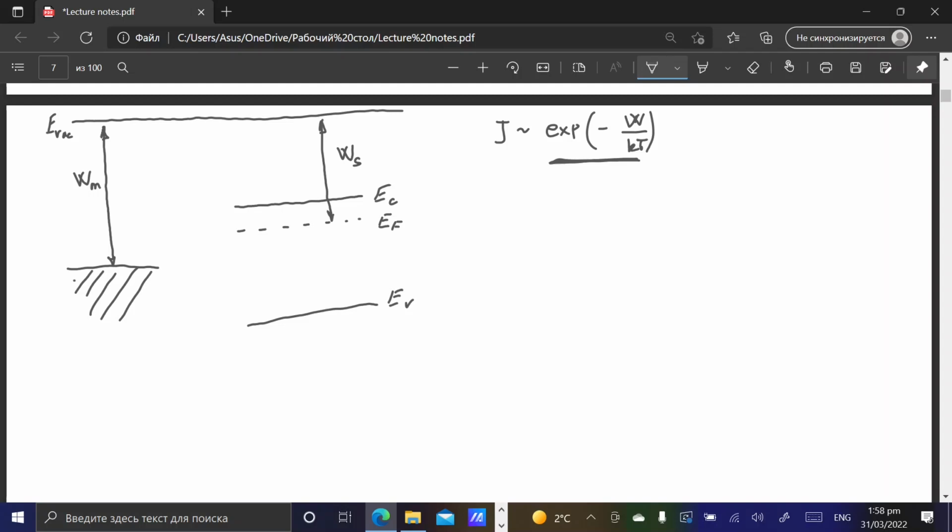So when this happens, what will actually go on at this interface? We will start to build up some space charge, a negative space charge formed by these excessive electrons, from the net flux of electrons from the semiconductor to the metal.